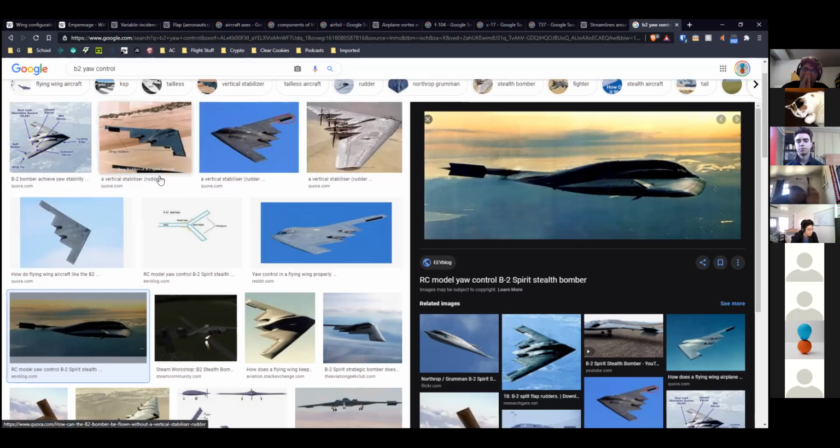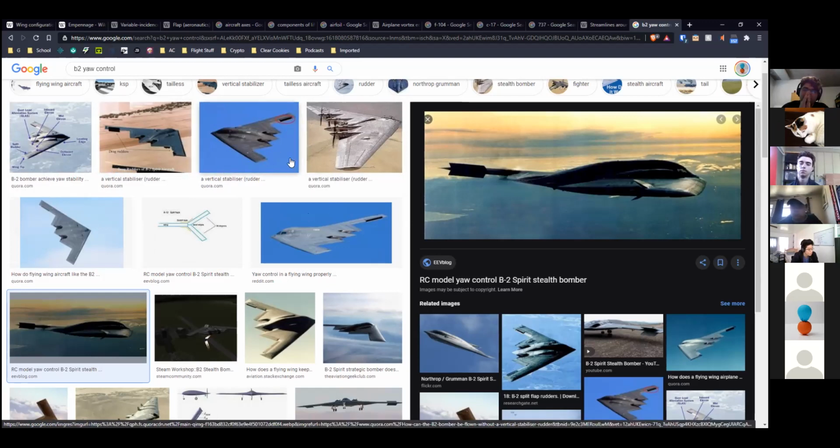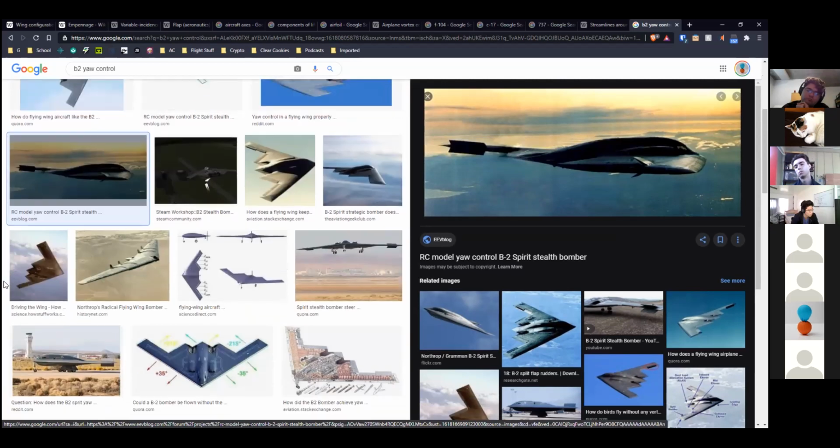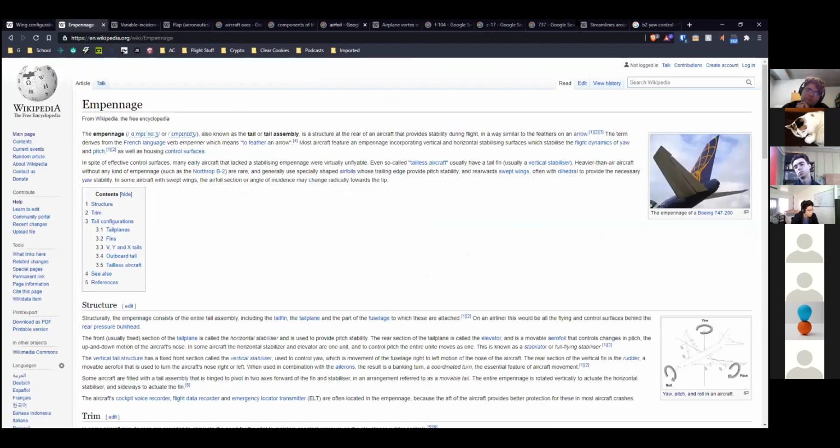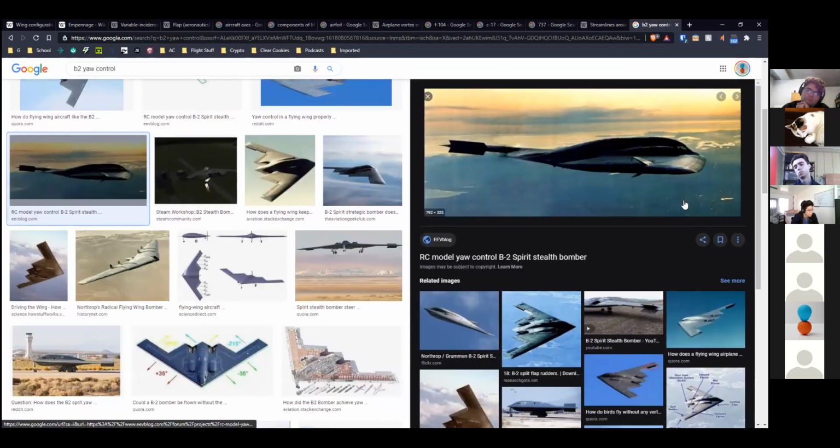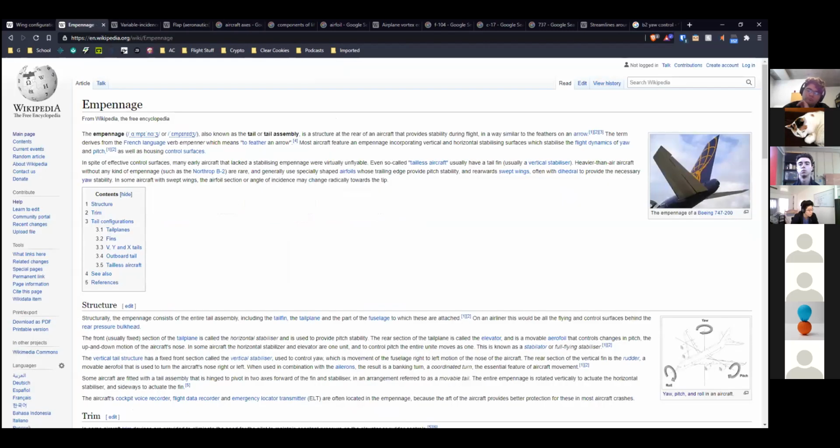But on any twin engine aircraft, the torques cancel out because they spin the engines in opposite directions. And also they have yaw dampers now. So basically you don't have to use the rudder almost ever on a modern aircraft, but it still needs to be there so that the computer can do it for you, or you just have something to keep yourself flying straight. You just don't need to actively change it very often.